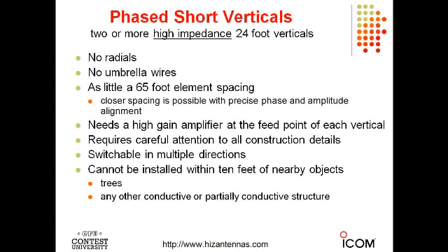But what we've now discovered, and many of us have implemented, is we can now build transmitting antennas that are optimized for transmitting, and we can build receiving antennas that are highly optimized for receiving. And we don't have to strike this compromise between the conflicting requirements between the two applications. So now you'll find the very best stations, including Tim's station, now have highly optimized transmitting antennas to make your signal loud.